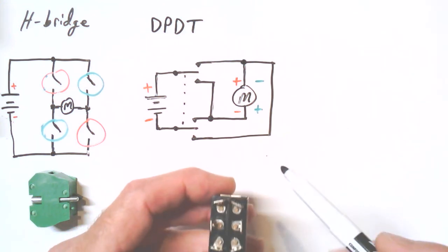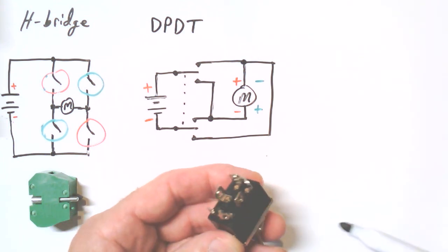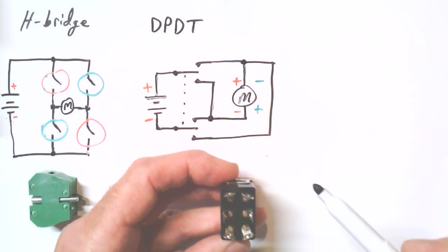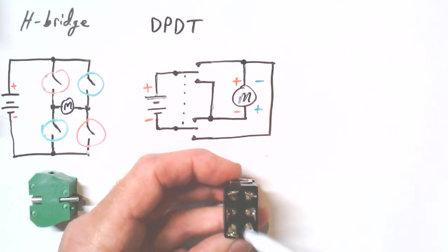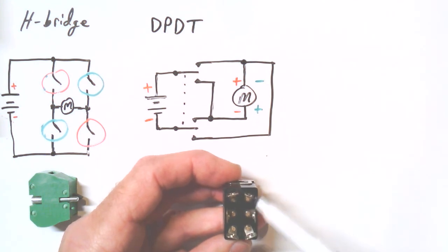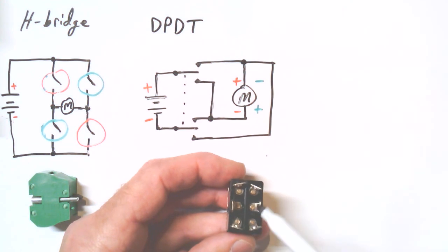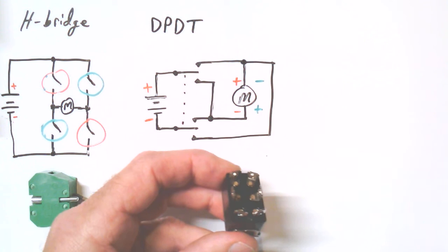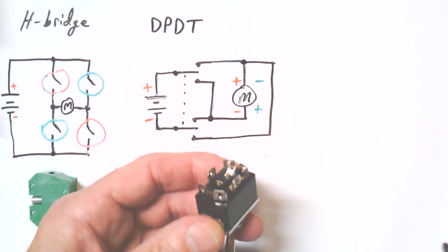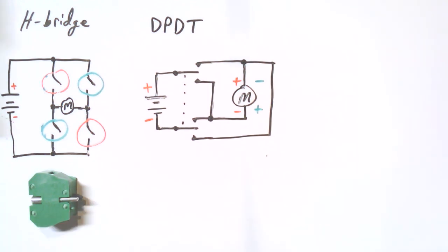So we're going to move away from a schematic to the literal thing that you will see. Maybe you've seen that in a cabinet, but it's a dead giveaway that they're doing polarity reversal if they have the crisscrossed, the throws sort of X'd, like this throw and this throw are connected together, this throw and this throw are connected together. That's a dead giveaway. And again, it's just a little trick to let you in on. It saves you time. You can recognize what's happening with that switch pretty quickly. I'll draw that literal thing on the board here.